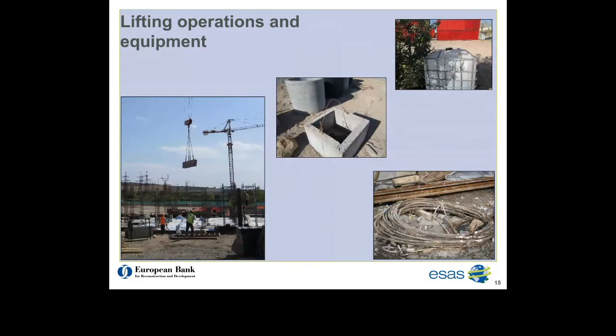With regard to lifting operations and equipment, the project requires extensive lifting of heavy loads, such as concrete culverts, manhole chambers, and ring beams. We noted the following concerns during the site visit. Lifting operations are not supervised by a trained, competent signaller or banksman, also known as a spotter. Heavy suspended loads are being lifted over the heads of workers, as you can see in the left-hand photo. This risk should be eliminated, or where unavoidable, suitable protection should be put in place. For example, the installation of a crash deck.